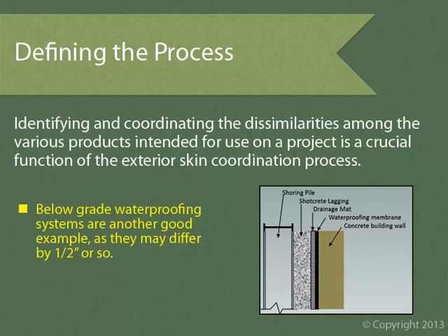If you find out the shoring encroaches too close to the building wall at the time you're beginning rebar installation, as often happens, you're going to be in big trouble. There's no way to push the shoring back, so you're going to have to go hat in hand to the design team asking for a significant structural revision. And that's never fun, usually very costly, and really pretty embarrassing when it happens.